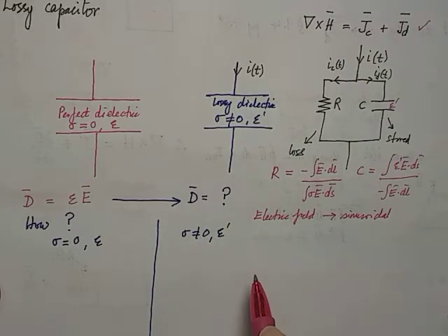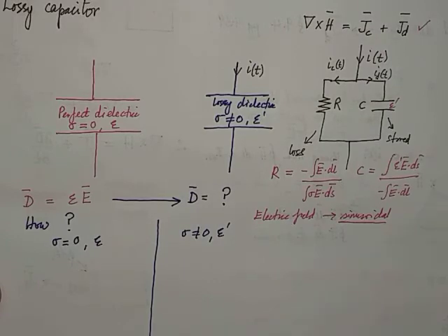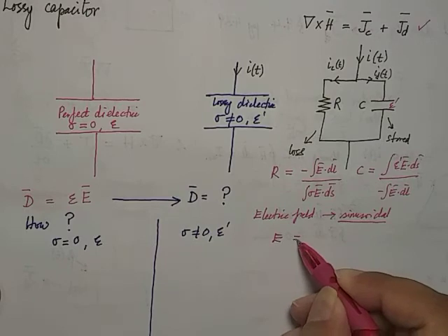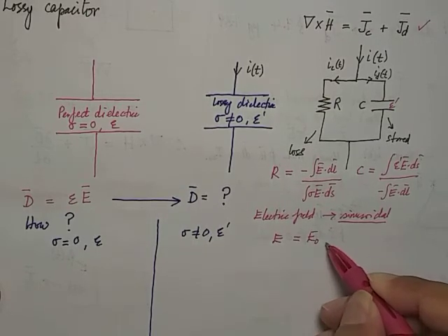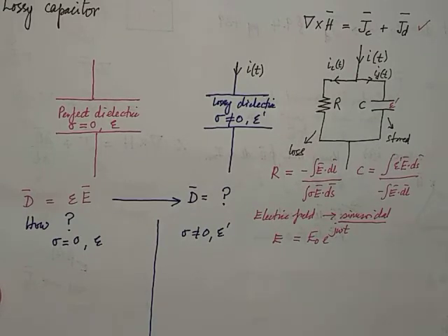Magnetic field also we always assume to be sinusoidal. Okay, sinusoidal is the important term here. So actually, how do we represent a sinusoidal wave? Good. So meaning that the E, I can denote it to be E naught exponential j omega t. Correct? Because we always model our wave to be sinusoidal. So when you see the term sinusoidal, you can represent that particular parameter with this exponential j omega t.